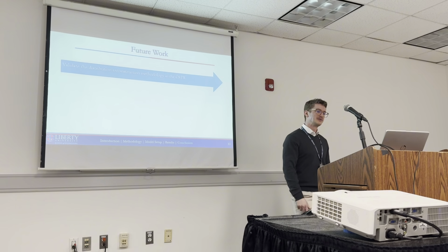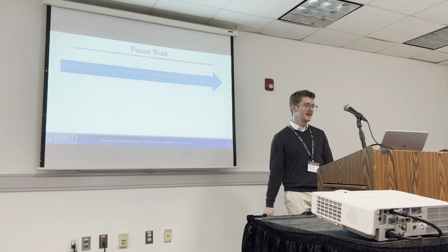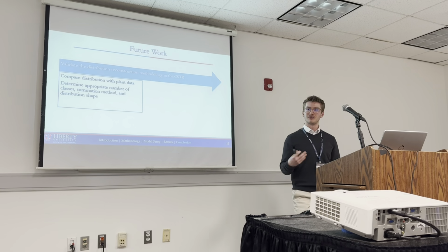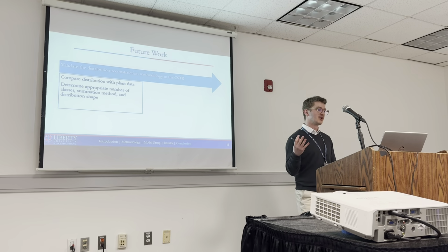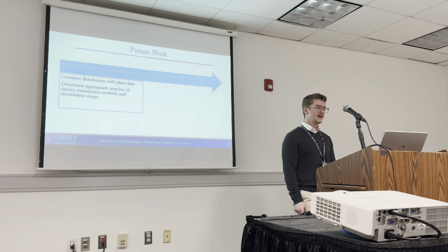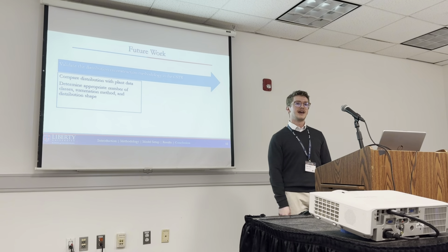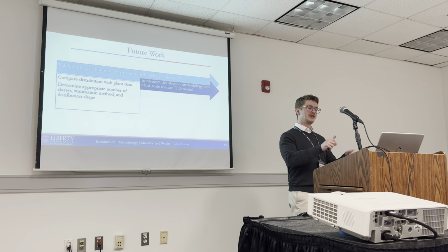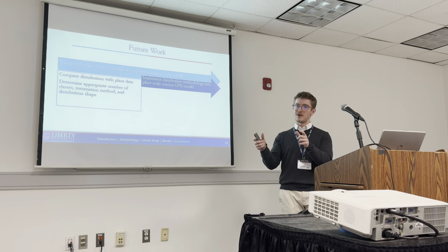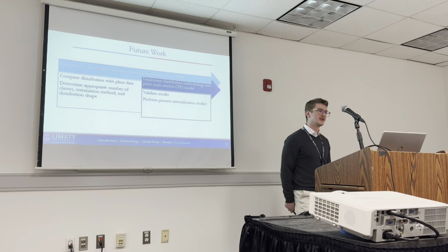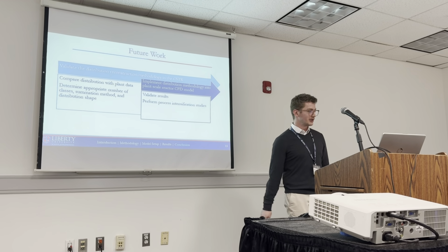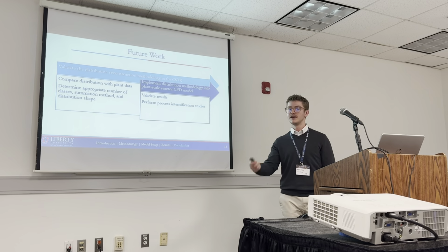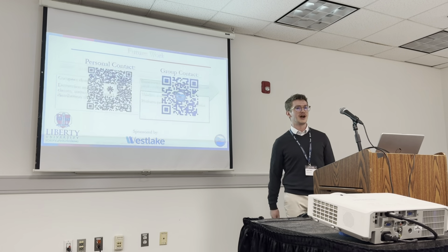So in the future, we hope to validate this distribution reconstruction methodology in the CSTR by looking at industrial distributions, comparing it with plant data, and hopefully determine the appropriate number of classes we need to replicate that, what the best method is for summation, and what statistical shape provides the best match. And then take that methodology and implement that into a plant scale reactor model in CFD. Do the same thing there, validate results, make sure we're still spot on relative to our industrial partner, and then perform those industrial process intensification processes to improve that reactor process.